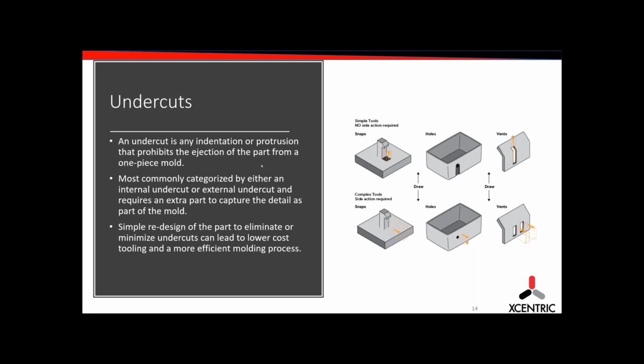Is the relationship between depth of part and the draft required? Yes, that can have a huge effect on design. Usually, every inch you want to add another half degree of draft.